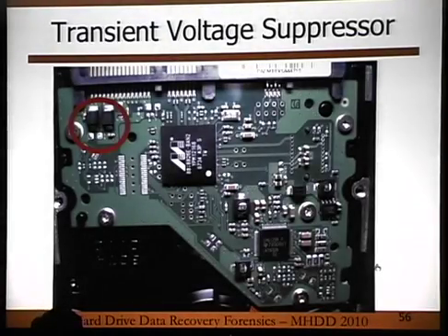Well, they have a voltage suppressor on them. Anybody remember the keyboard fuses? Remember back in the early days in the ATs and XTs? Yeah, some of them are older. All right, and how'd you fix the keyboard fuse? Jumper it. Yeah, you jumper it by sticking a penny in it or something like that, right? So the keyboards had a fuse that if it blew, rather than blow something on the motherboard, you would actually have to resolder it on the motherboard itself, to prevent the motherboard from dying.